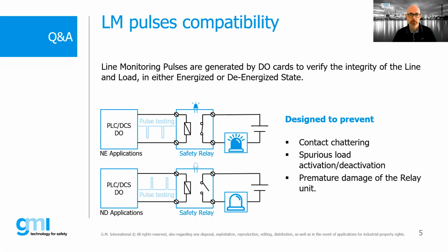Compatibility with this pulse test is very important in a safety relay, first of all to allow the correct test of the line, and moreover to avoid that these pulses cause a chattering effect in the relay, spurious activation or deactivation of the load, as well as damage of the relay itself.